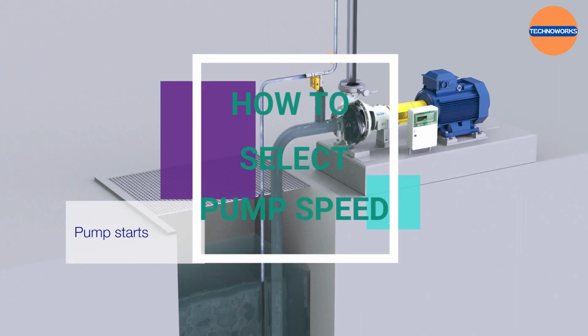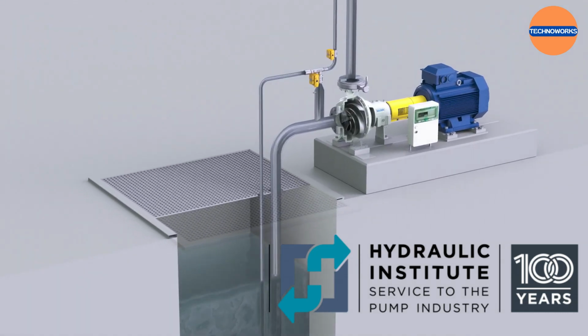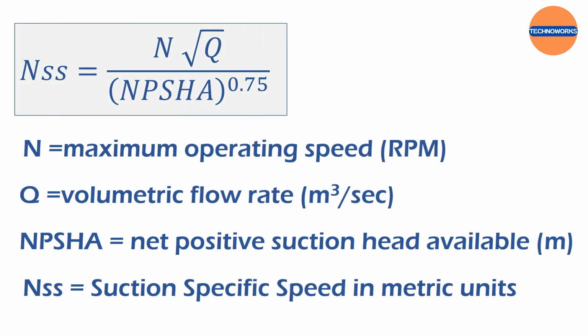Now, I will show you how to select the pump speed. As per Hydraulic Institute standard, pump suction specific speed can be used to estimate maximum operating speed. This equation may be used to calculate the maximum operating speed.